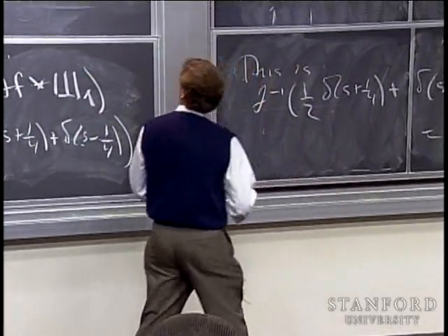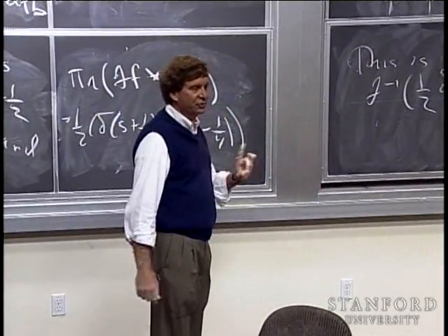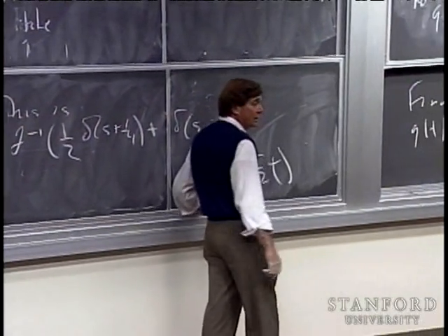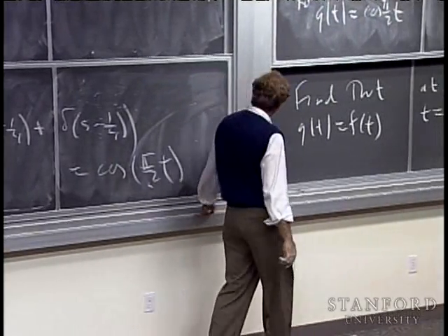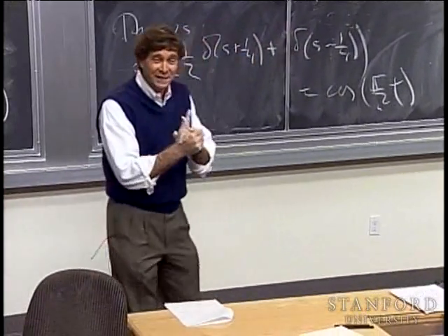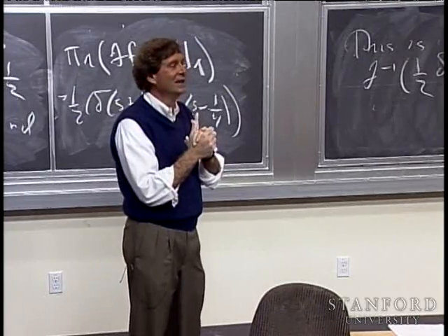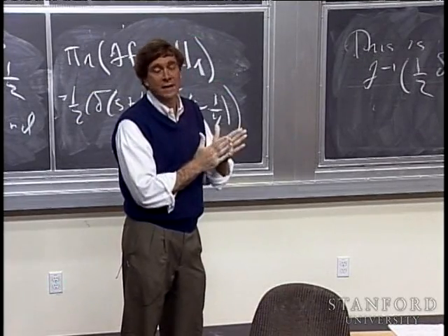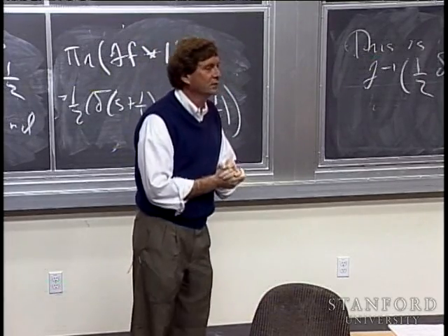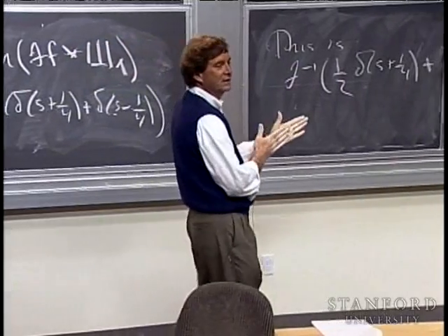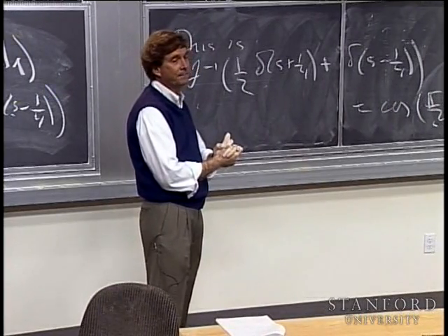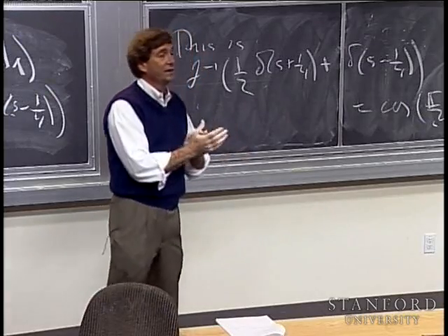All right? In the sense that the fundamental equation, the cutoff of the periodized Fourier transform, does not give you the Fourier transform back. All right? That fundamental equation is not satisfied. All right? And so what you've come up with is something different. Okay? This is sort of the natural phenomenon that's associated. Aliasing is, so to speak, the natural phenomenon that's associated with the sampling theorem. All right? But it is nothing other than doing the right work sort of in the wrong cause, so to speak, all right, by taking the wrong sampling rate, by taking a sampling rate such that the fundamental equation is not satisfied. Okay? All right, that's all I wanted to say on this, actually, as much as I love this topic.